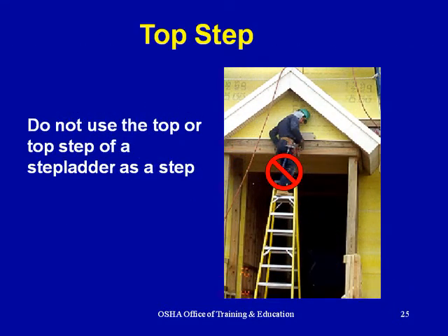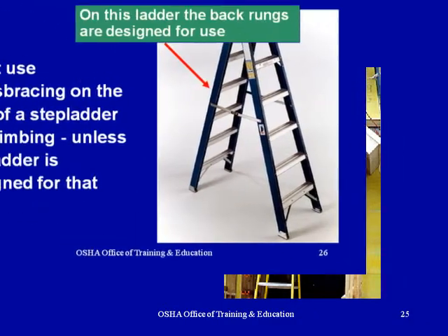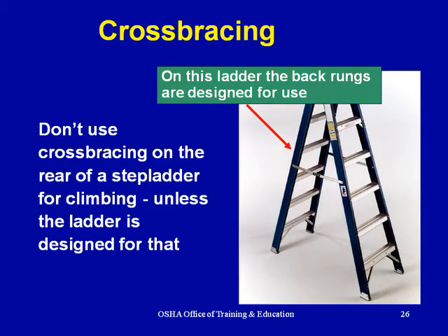Top step. Do not use the top or top step of a step ladder as a step. Cross bracing. On this ladder, the back rungs are designed for use. Don't use cross bracing on the rear of a step ladder for climbing unless the ladder is designed for that.